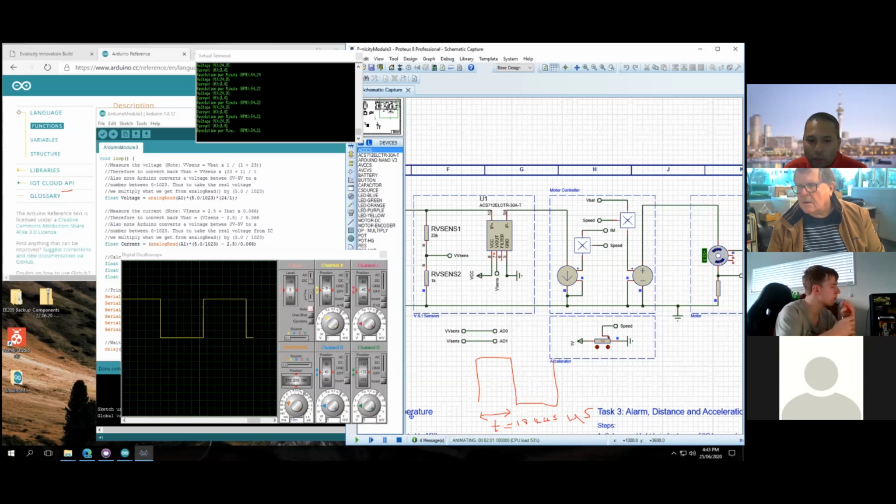In a normal car, when you're braking, the friction in your brake system dissipates all that energy and wastes it as heat. Whereas in an electric vehicle, all that current goes back into the battery, charging it. So you get back the energy rather than wasting it. So there you go. When you're at very low speed, the current is very small. It's running at very low RPM. Battery voltage has come back up to 24 volts.